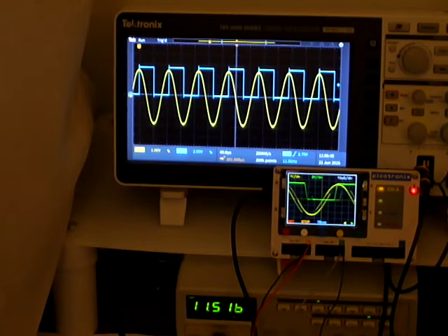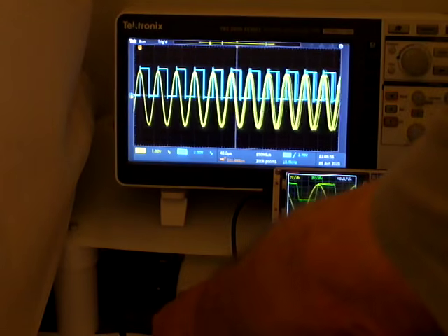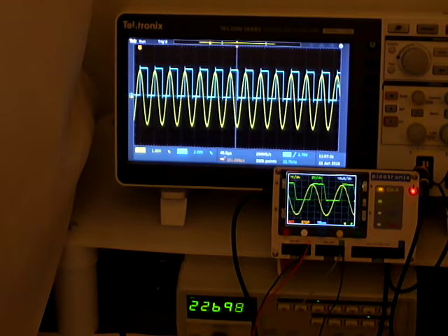Just as a final thing, at the fastest sample rate, we're looking there at 11 kilohertz, so we can go faster than that. Once we go past 20 or 30 kilohertz, we're starting to see some artifacts from the ADC, because it's doing a linear interpolation between the points. At that stage you have to start using different techniques or move to a faster ADC. But the ADC is maintaining the same noise levels at this, so I can turn the signal down.